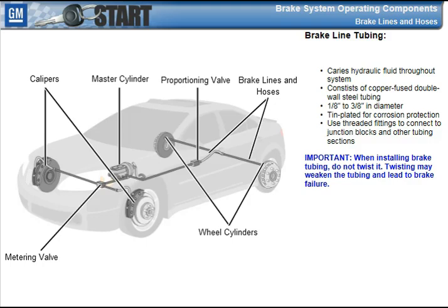Brake line tubing is connected to junction blocks and other tubing sections with threaded fittings. When installing brake tubing, do not twist it. Twisting may weaken the tubing and lead to brake failure.